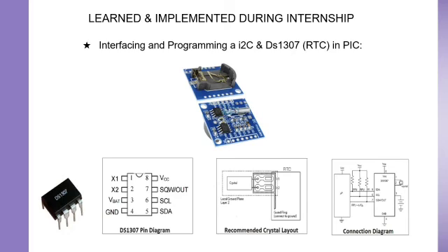Real-time clock (RTC) is used to track the current time and date. It is generally used in computers, laptops, mobiles, embedded systems, application devices, etc. In many embedded systems, we need to put a timestamp while logging data, in other words, sensor values, GPS coordinates, etc. For getting a timestamp, we need to use RTC.